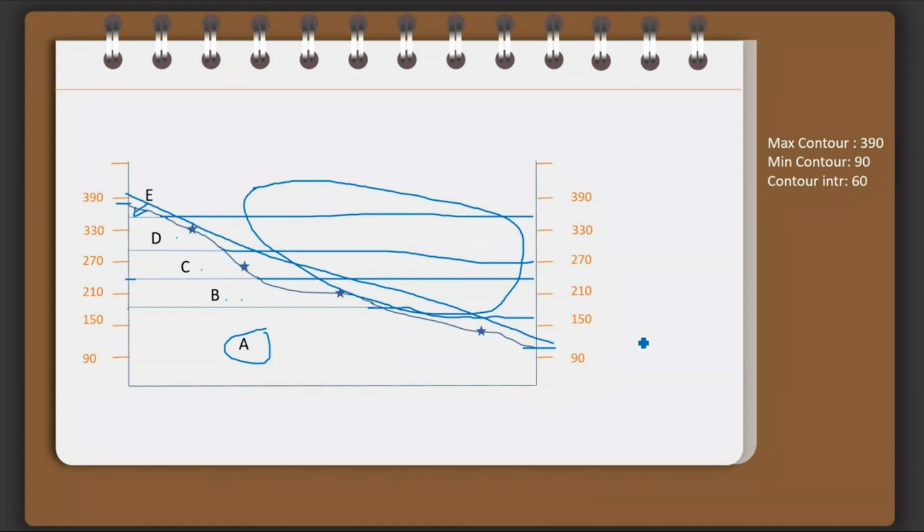So there is no indication of structural features, and if you know the physical or mechanical characteristics of these rock types A, B, C, D and E, I can even decide at what depth my foundation would go, and whether I would be able to consider this region for the construction of a dam or not. All the different factors I can understand from the geological cross-section.